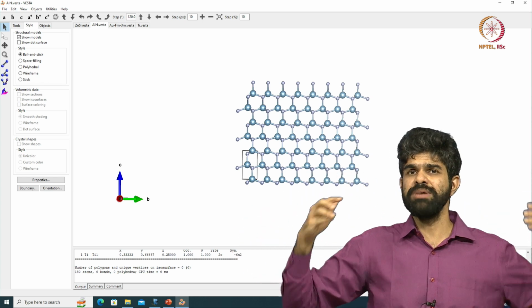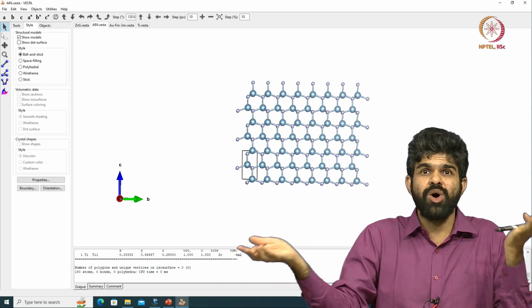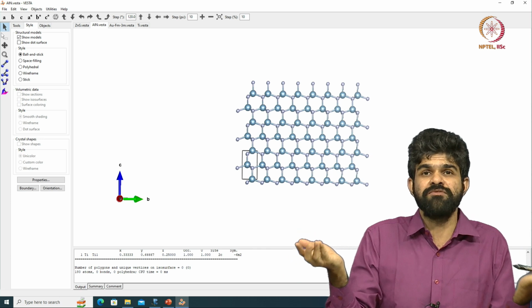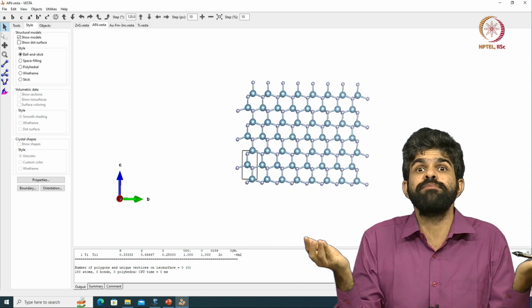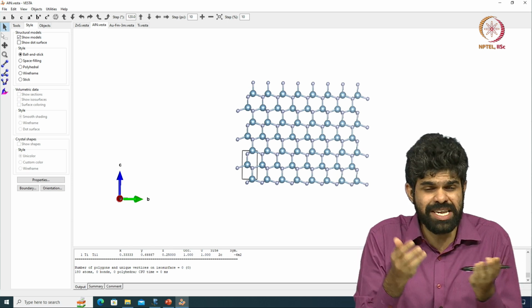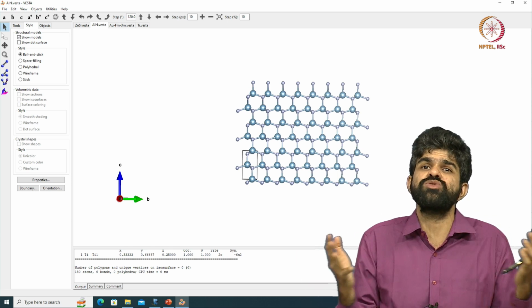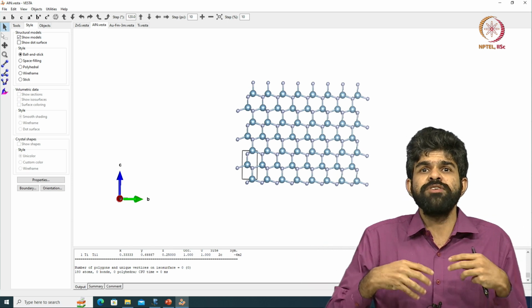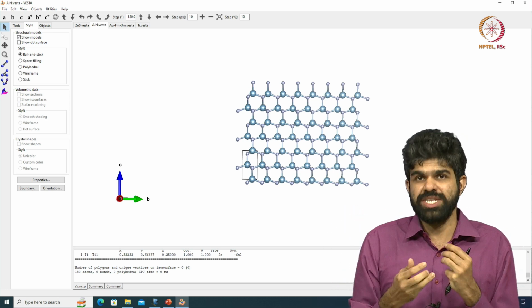Now, it turns out that many materials can crystallize in either Wurtzite or zinc blende, they are energetically sort of equivalent, like I was telling you about cadmium telluride, right. Energetically the zinc blende and the Wurtzite structure are close to each other, so if I am growing cadmium telluride I can get both structures, right.